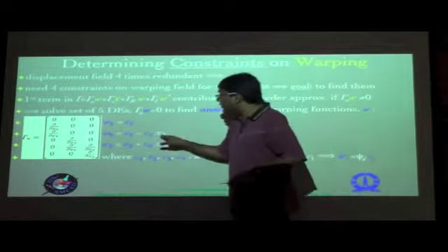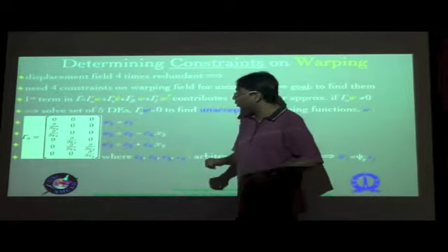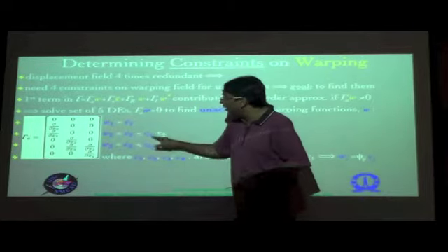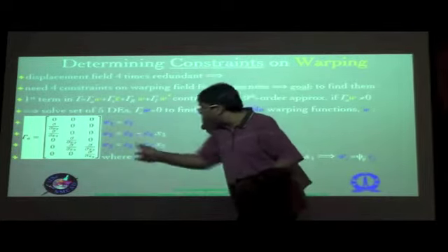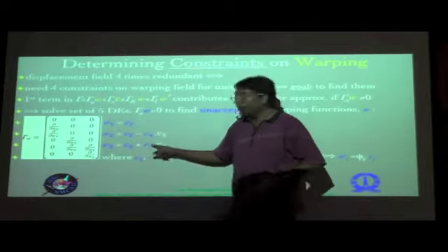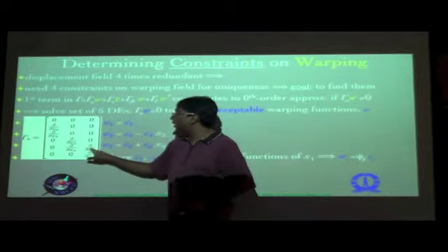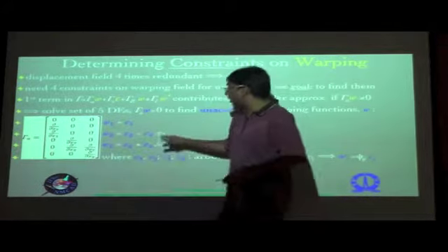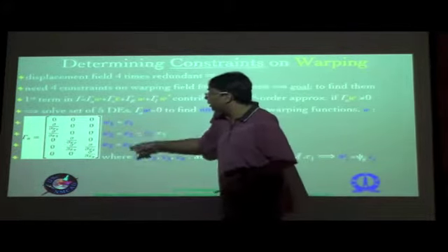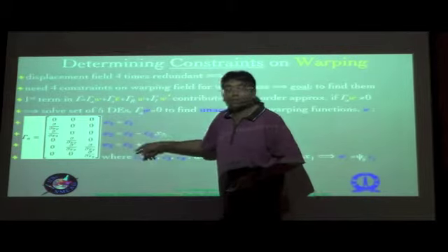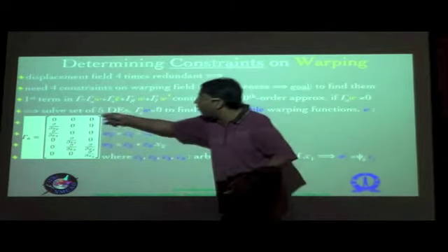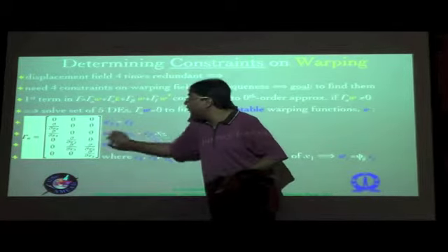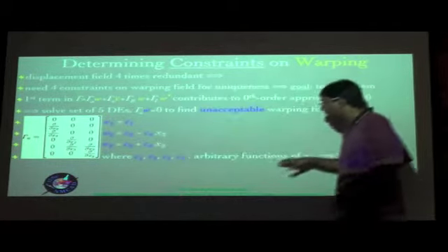But you see that W2 is a function only of x3, W3 is a function only of x2, and in such a way that W2, 3 is C4 minus C4, and W3, 2 is plus C4, so that this equation is satisfied as well with C4 minus C4 equal to 0. Okay, so that is satisfied as well, and of course a constant is still acceptable in each one of those terms. So this is the general solution you have when you have these differential equations solved simultaneously.